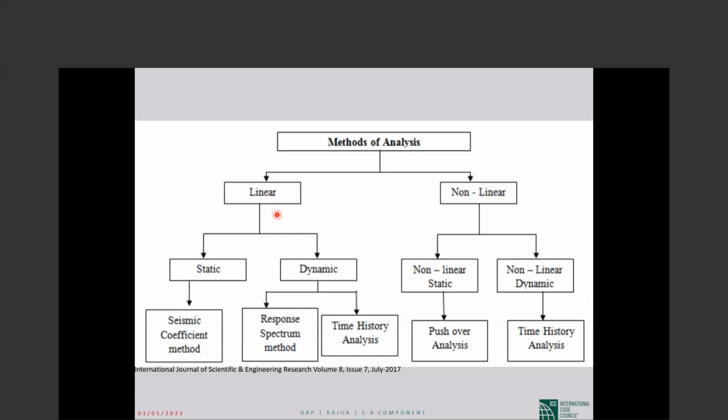So from the systematic evaluation point of view, each material, each different element of the building has two values, two strengths. One is the expected, the average, if you do tests, the average value, and one is the lower bound, average minus one standard deviation. So the material is the same, but the value that we use for the force control actions, for the scary ones, we use a smaller value for the strength of it.